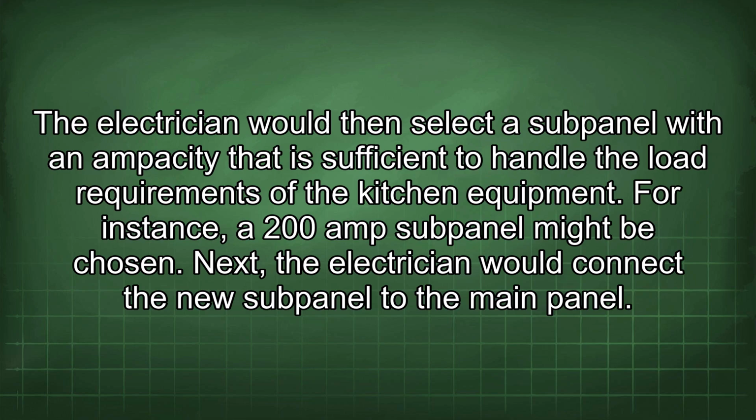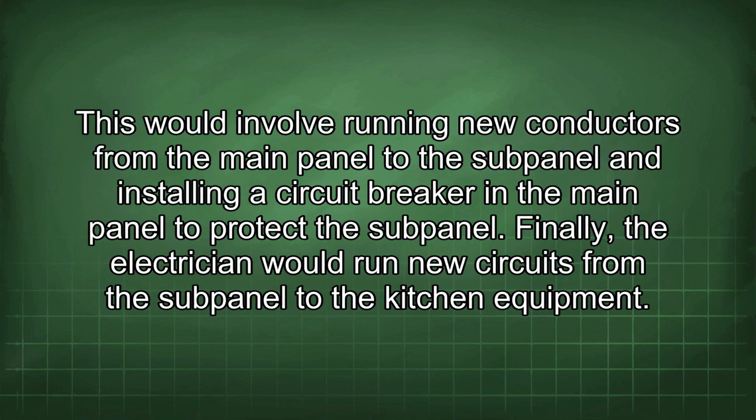Next, the electrician would connect the new subpanel to the main panel. This would involve running new conductors from the main panel to the subpanel and installing a circuit breaker in the main panel to protect the subpanel.